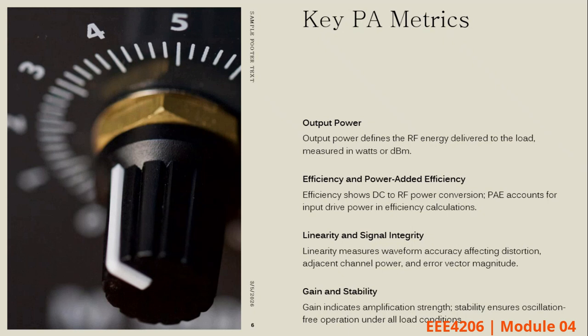That means if we are choosing the class of the amplifier, we need to ensure that the linearity aspect of it is looked at critically. Otherwise, you have some interferences, and you might interfere with the neighboring channels in the frequency spectrum, or adjacent channel power, and also you have errors in your transmitted signal.